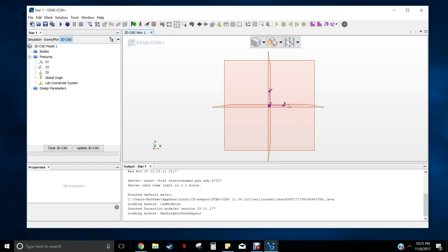The first thing we're going to do is create a sketch. You want to create that sketch in the XY plane. Because it's only going to be 2D, you want everything to exist in the z = 0 plane. So in order to do that, you can just make your sketch on the XY plane. Right click on it, and then click create sketch.